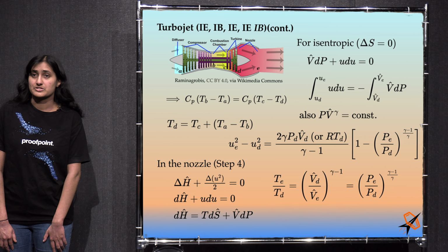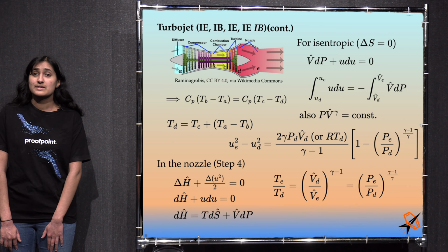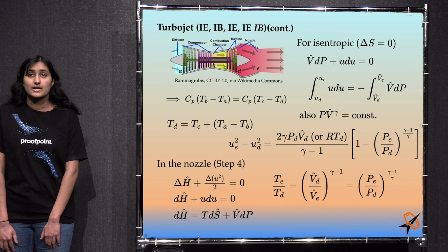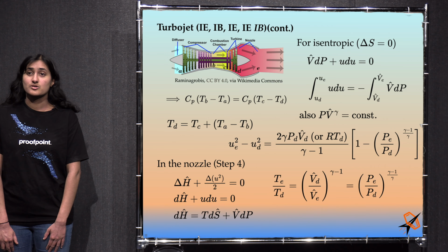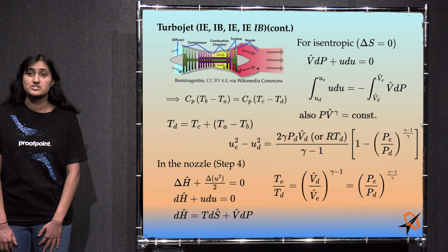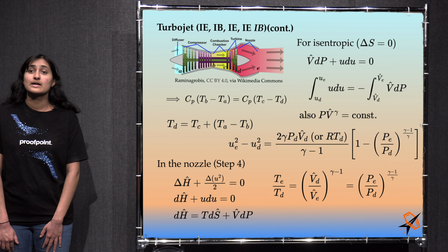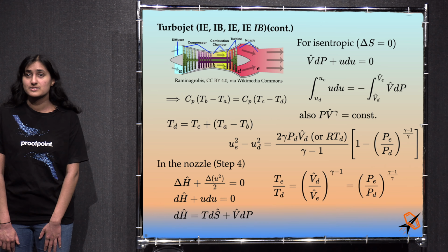When performing these calculations, keep careful track of your units or you may not end up with velocities at the end. Wikipedia has a lot more information on turbojets. In turbofan engines, which are the most common type these days, more power is extracted by the turbine to drive large fan blades that drive air that bypasses the compression, combustion, and expansion stages, which increases the efficiency and quiets the engine substantially. Wikipedia also has much more information on turbofans.